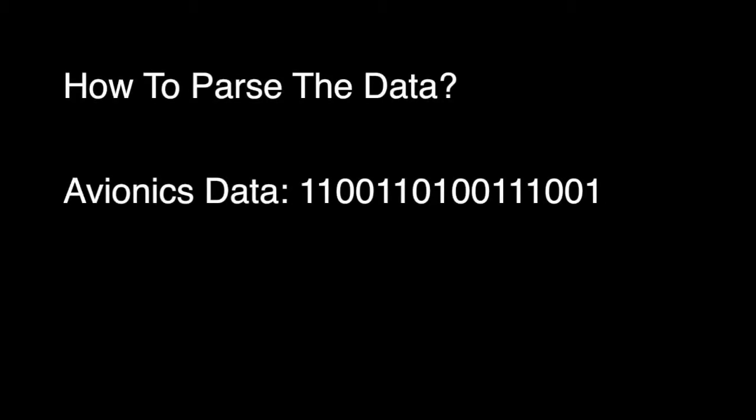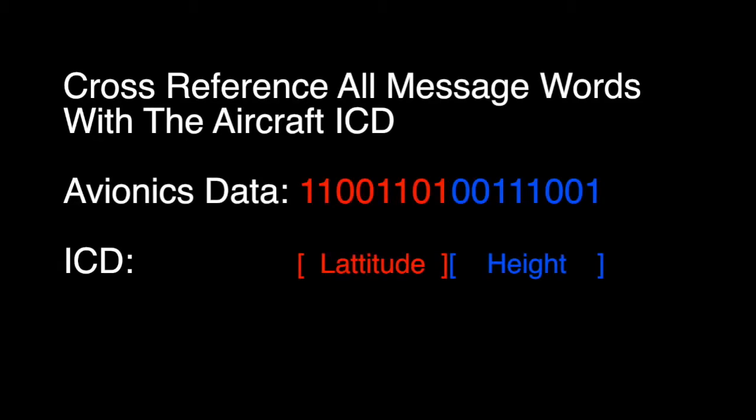Hi! Avionic in-aircraft communication is monitored and recorded on a bit-by-bit level. In order to pass all the relevant messages for post-flight system analysis or debugging, there is a need to cross-reference all message words with the aircraft's ICD. In the next few minutes, I am going to use the engineering unit capability of the Sital Composer to display parsed data with no scripting or coding.